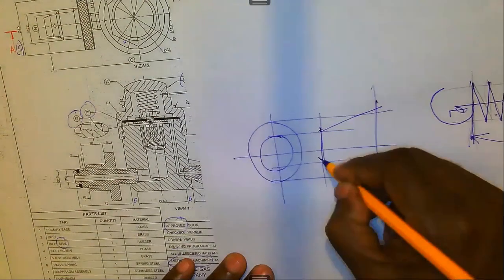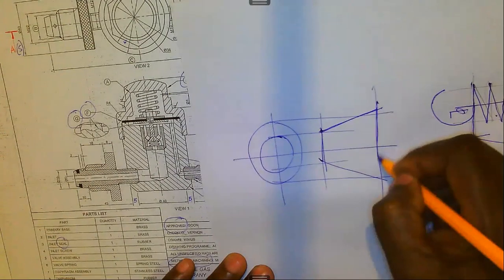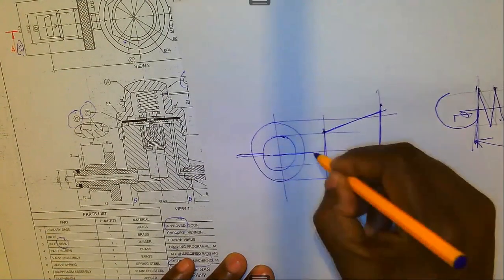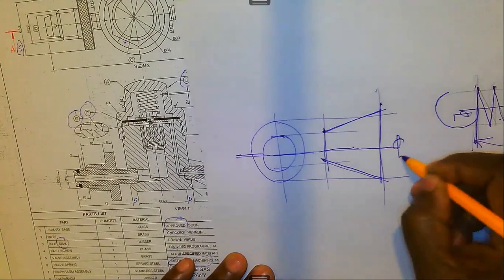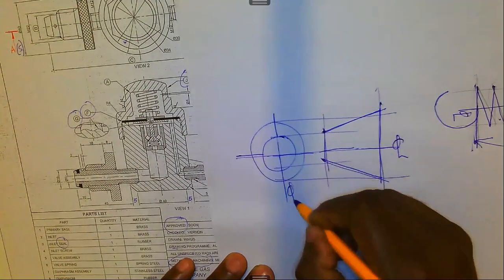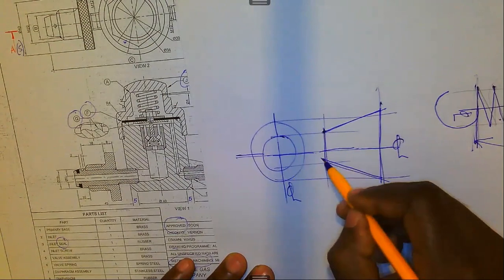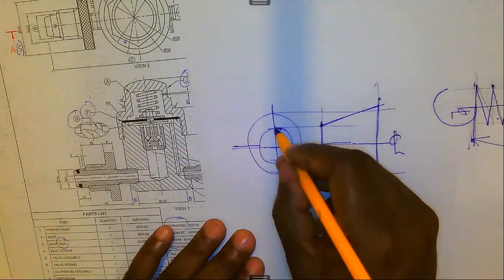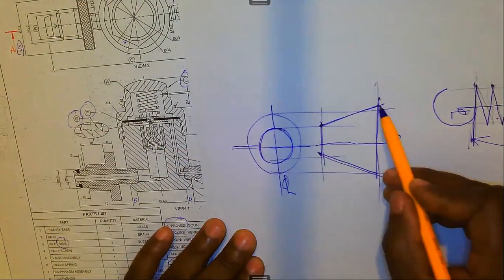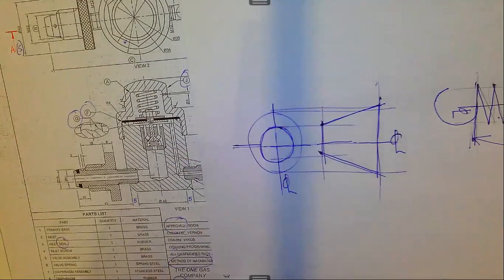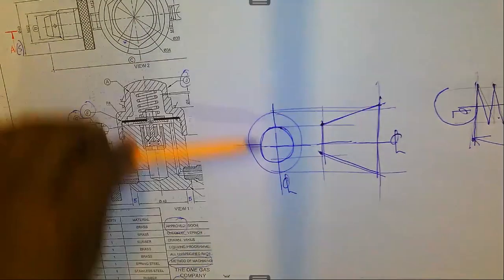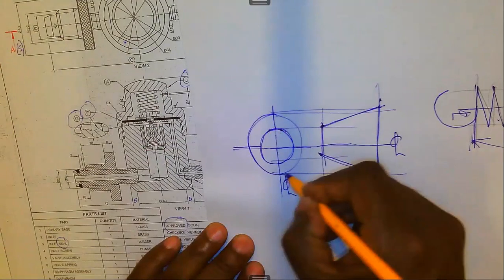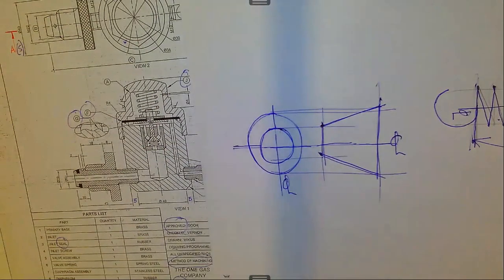So this is a truncated cone, right? Like that. You need center lines like this. You also need a vertical center line like that. Right, so this part which has been cut, when you are looking from the left-hand side, is the one that is drawn here. Right, this is the base. When you are looking from the base, you look at that, you take it back, and you draw that one like that. So this is a typical third angle system symbol in terms of system of projection.